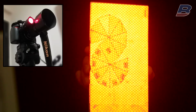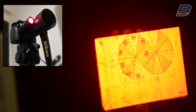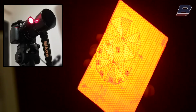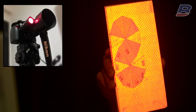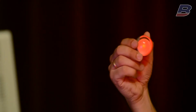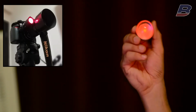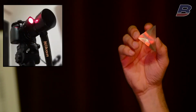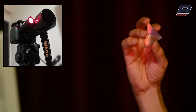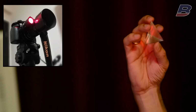At narrow entrance angle, you won't see a big difference until I make the entrance angle wider. The wider the entrance angle, the bigger the difference in retroreflection. This effect is caused by lack of symmetry in optical elements used in microprismatic sheeting. Take a look at how consistent the retroreflection of spherical elements is, no matter how I rotate and position it, and how the retroreflection of corner cube prism varies when I change its orientation. At a certain point, the retroreflection effect disappears.